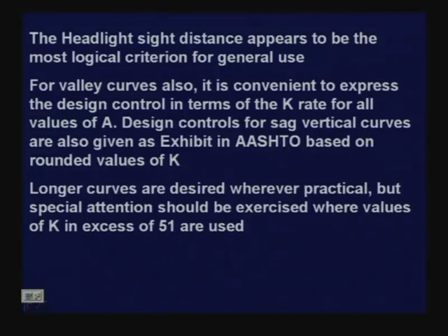Longer curves are desired wherever practical, but special attention should be exercised where values of K exceed 51. That means special care is needed when the value of K is more than 51, particularly considering the drainage part.